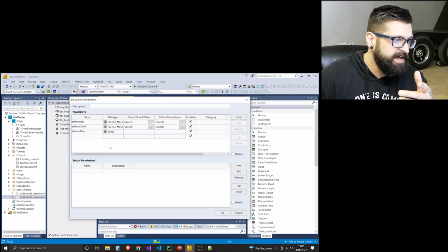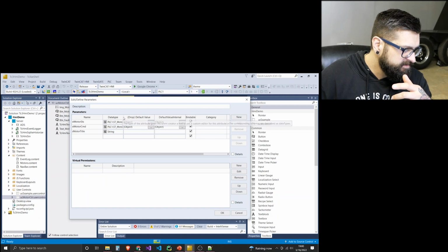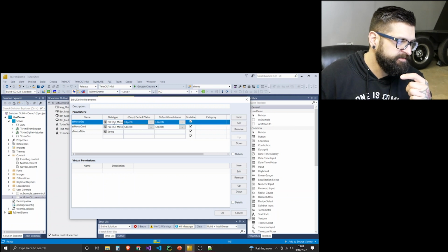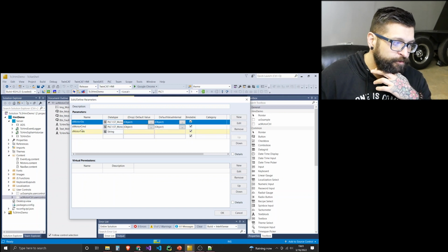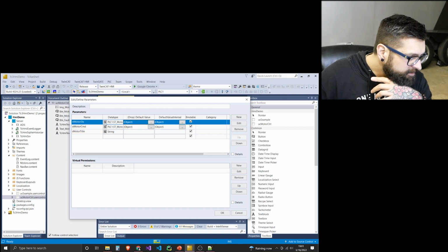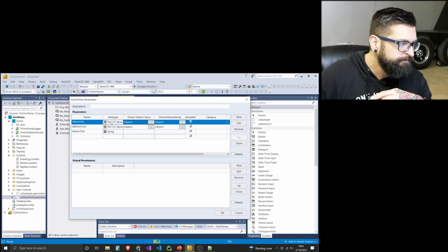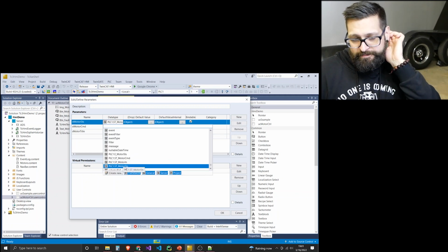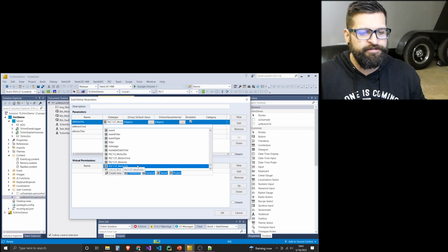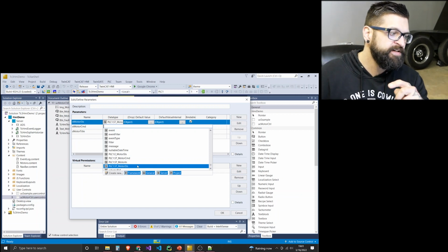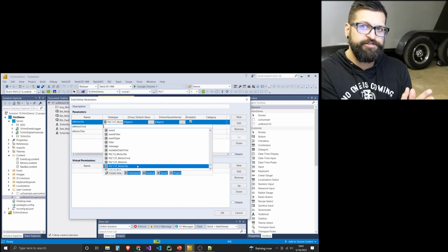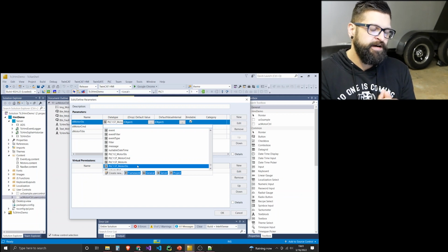So what I've done is I have a data type called ST. See if I can get this thing to spread out. I might not be able to, but I've got three parameters. This is the local variable name: ST motor status, ST motor command, and S motor title. Because I mapped these from my PLC, let's see, yeah, down here. If we look down here, we can see that when I mapped the symbol from the PLC to the HMI server, it created that type. It said, okay, I see this structure, and I'm going to create this type, and now I know how to use this type.